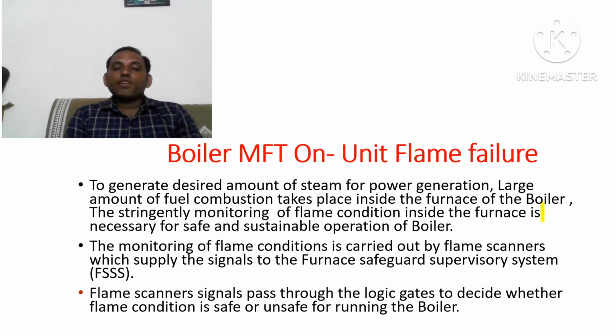The monitoring of flame conditions is carried out by flame scanners, which supply the signals to the furnace safeguard supervisory system. Flame scanner signals pass through the logic gates to decide whether the flame condition is safe or unsafe for running the boiler.